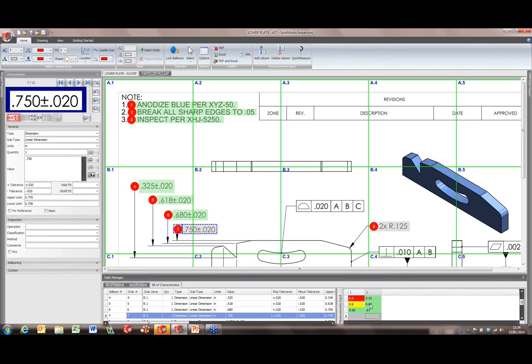So on test number 2, or inspection number 2, everything we've inputted has passed. On inspection number 1, a couple of things failed and something was quite close. So if you've got a small sample out of a batch, we can see across that sample a history, maybe over a period of weeks or months, to test whether things are deteriorating or getting better based on machine tool wear and that sort of thing. So we can keep track of all that.